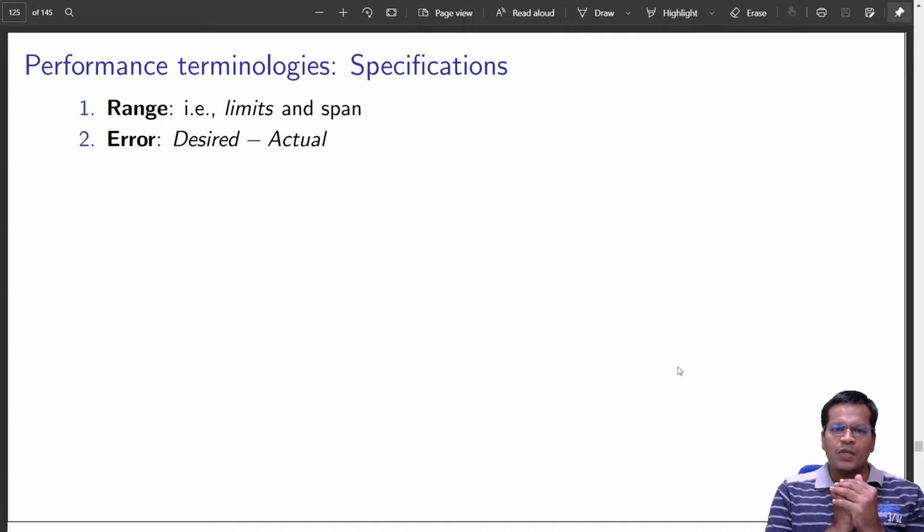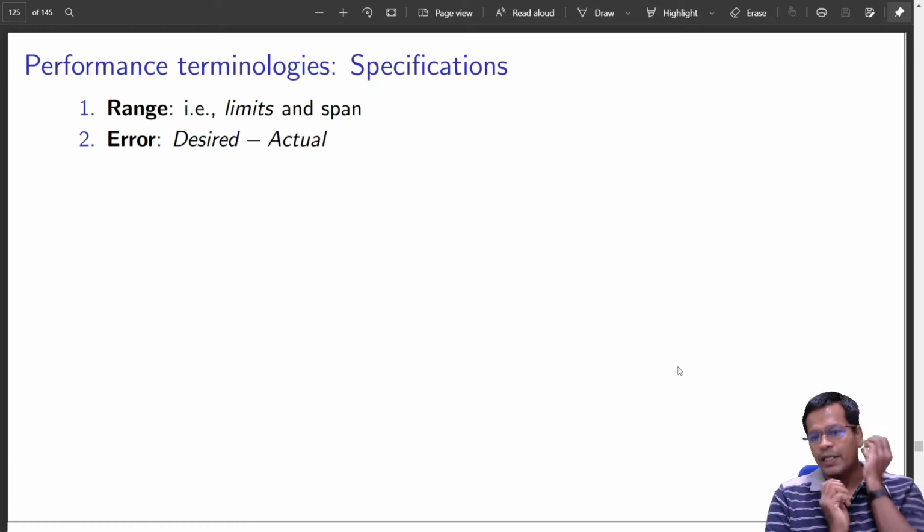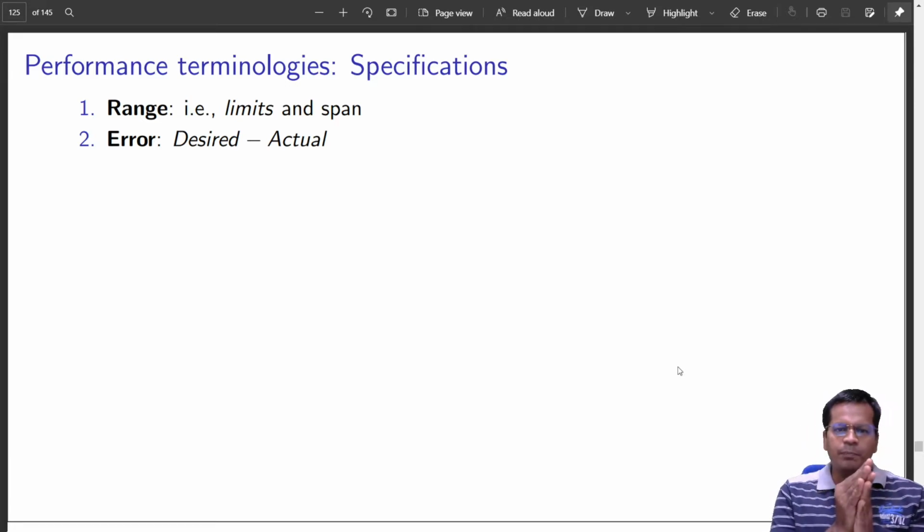Okay, if it is an optical sensor, it will be a little expensive. If it is a potentiometer, they are quite inexpensive. But yes, different sensors have their own limitations in terms of desired and actual. If it is 5 mm, that is the displacement I wanted to see, but actually your sensor is showing something around 5.01 mm. If I am happy with this for my particular application, that is fine.